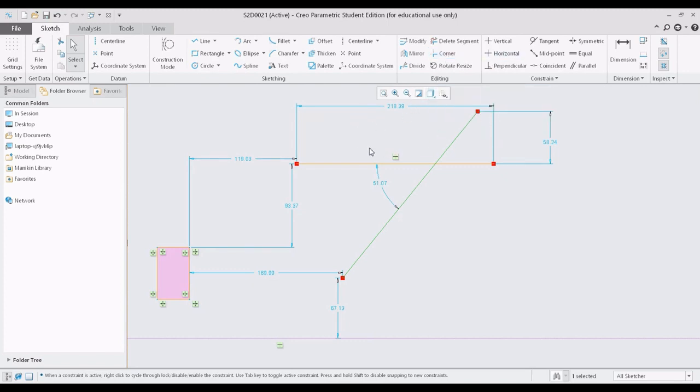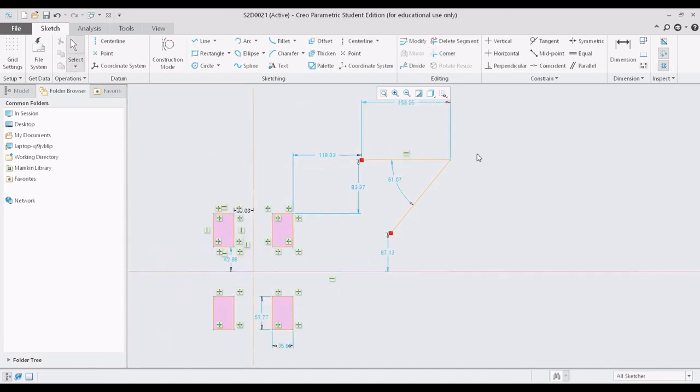So whenever I want these two lines to form a corner, I have to delete this segment, this line, and I have to delete this region of the line. Okay, then I will be having a line in this fashion, in the cross fashion, okay, slanted fashion. So let me just try to show you the corner option. I have to click on corner. So it is nothing but selecting two entities to trim the extra portion of the entity. Select the first line, select the second line. There it is. The additional region has been trimmed off. So this is the function of the corner option.